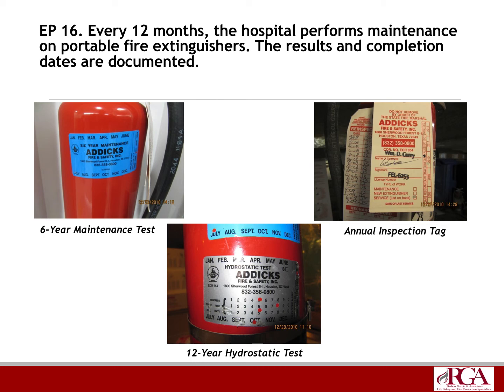Now, another bonus note for your Class K fire extinguishers that are in your kitchens: make sure they have a sign, a placard above it, that states for you to activate your kitchen hood system prior to using your fire extinguisher. This is kind of contradicting from what we're taught in healthcare, because we're always taught PASS, right? Pull, aim, squeeze, sweep. But in a kitchen fire, they actually want you to activate the kitchen hood suppression system prior to using the Class K fire extinguisher. And you have to have that sign above. It's a red sign above the Class K fire extinguisher.